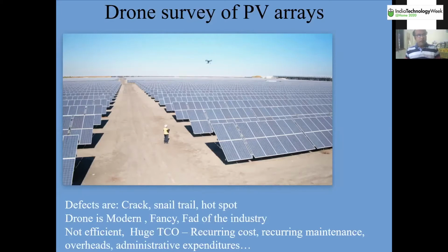My company also deploys this drone. Huge drones are deployed. But really, I'm telling you, at the end of the day, the supervisor has to make a round and find out whether any panel is burning or not. Yes, a lot of burning takes place. Fire incidents take place on the back of the solar panels. So you have to be very vigilant. And the main indication you will find, if you go through in detail, is that gradually and slowly over time the contribution of the panel reduces.